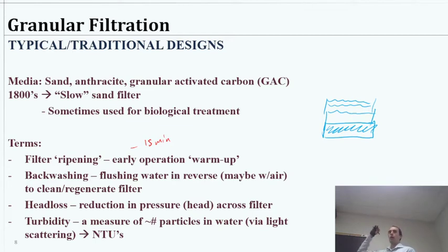Then, whereas at the top we had 10 psi is our pressure in the pipe, then in the pipe in the lower we'd have 5 remaining. Okay, that's how a pressurized system like this works. That pressure is essentially consumed by the force required to push the liquid through the media. So then that would be a 5 psi head loss.